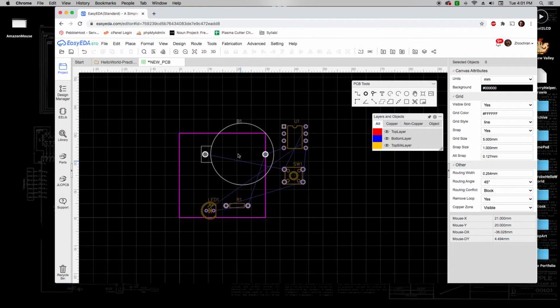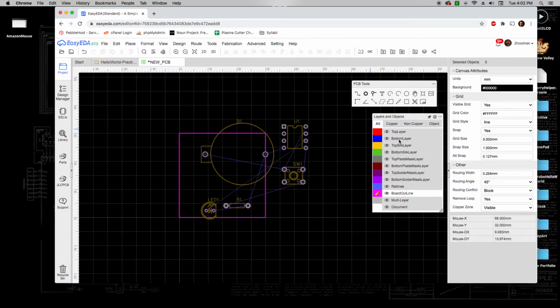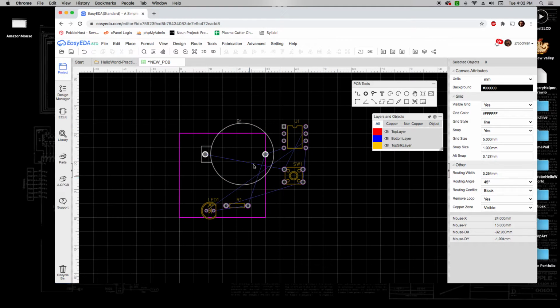Now you might be looking at this and be like, well, that doesn't seem very probable because all these components are quite big and I've got a small square. But one of the things that we're doing for this assignment is we're doing what are called two-layer boards. So that means we actually have a top layer and a bottom layer where we can put our components. And so we can actually stack them. In doing so, we need to be careful about some of the choices that we make. But I think if we're smart, we'll be okay.